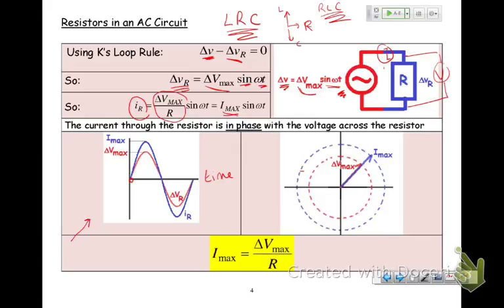So now we see the angular difference. If my voltage is at omega t, my current is at omega t minus pi by 2. And pi by 2 is 90 degrees. So this is 90 degrees behind. Okay? So mathematically we justified what we observe on the oscilloscope.